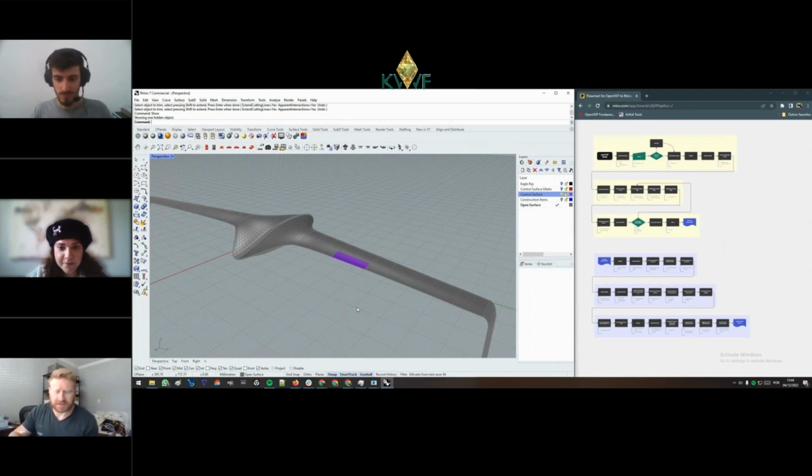Yeah, I just want to start off with some of mine. I don't really use Rhino all that much, but it seems a really versatile tool. So a lot of the steps that you were performing here in Rhino, the process makes perfect sense from a CAD perspective, that you're ensuring all of your lines are well intersected, that everything is tangent smooth, has a good rotation axis so that you don't bump into yourself when you rotate.